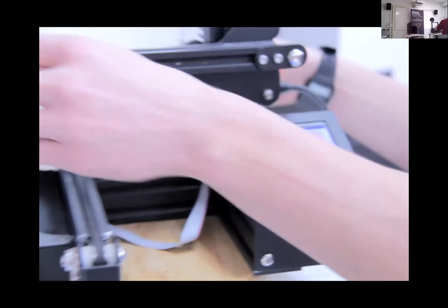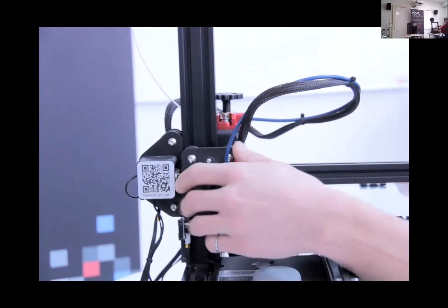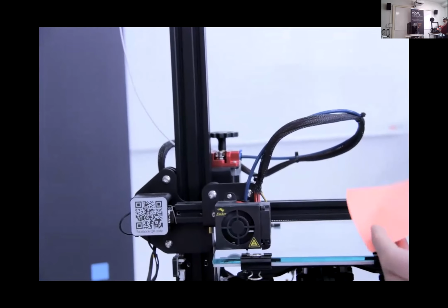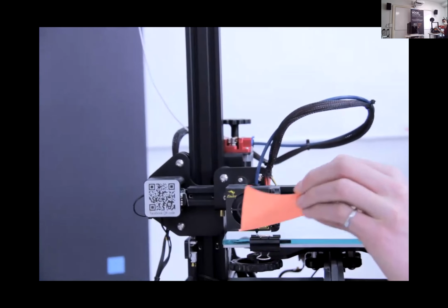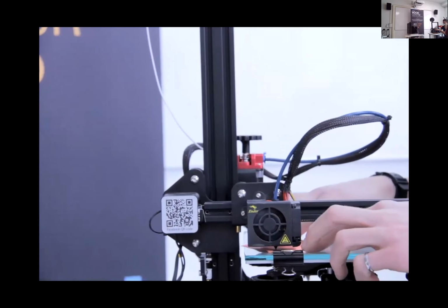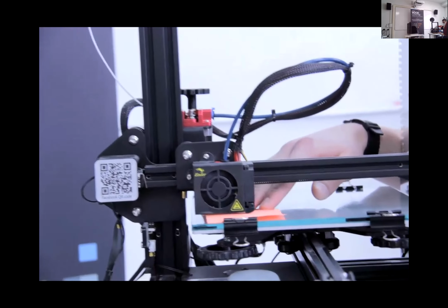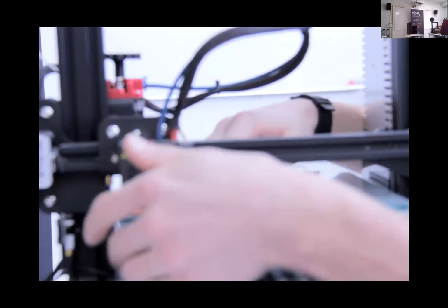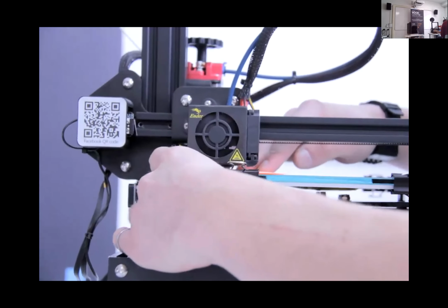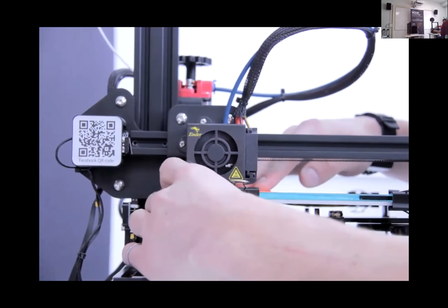So what I'm going to do here quickly is manually move my axes. So push the print bed, push the hot end to all four corners. And in each corner, I'm just going to slide this piece of paper underneath and double check that the nozzle is about a paper's thickness off. And you can kind of feel the nozzle rubbing on the paper. That's great. If it needed adjustment, there's some knobs under each corner of the print bed. And I can adjust these up and down, left and right, and feel how that affects the bed height.